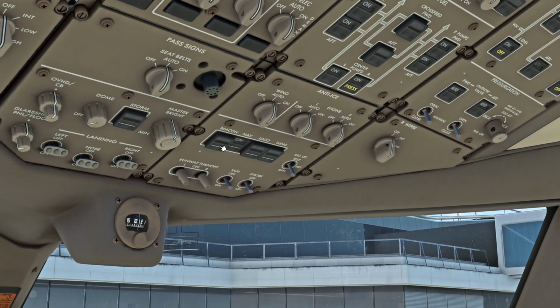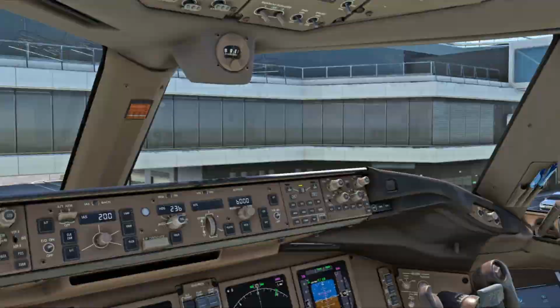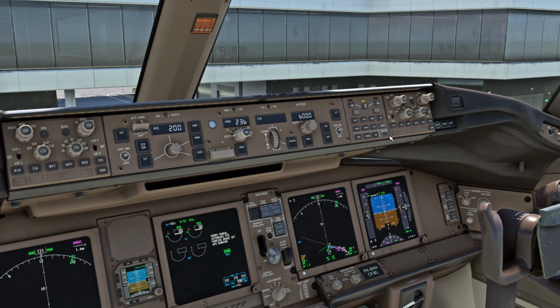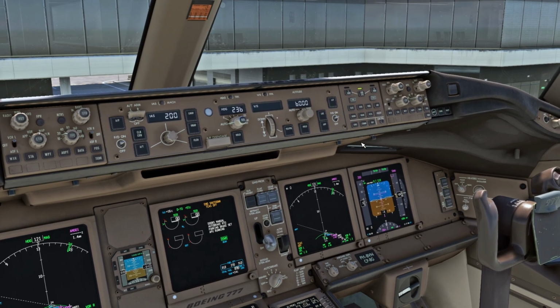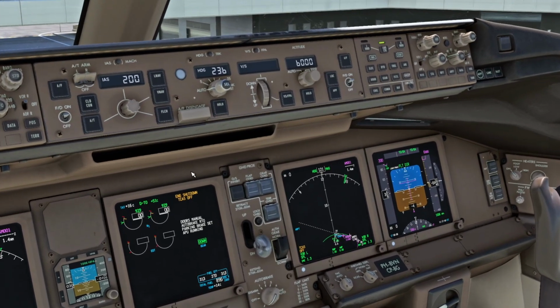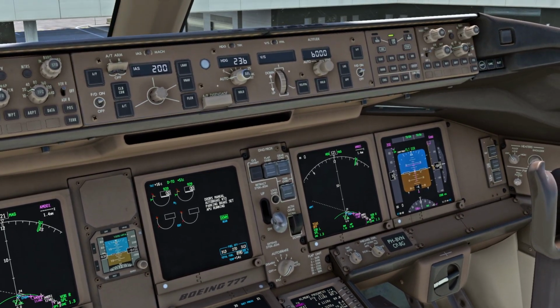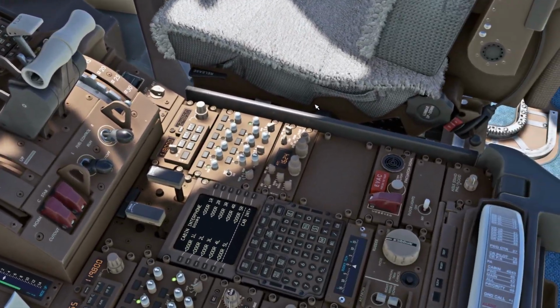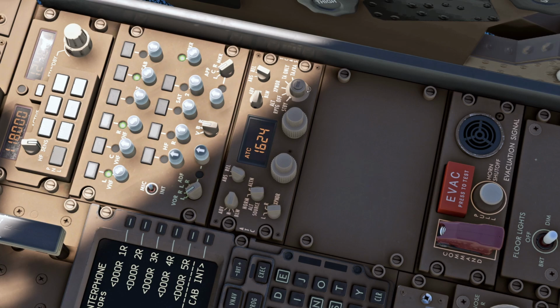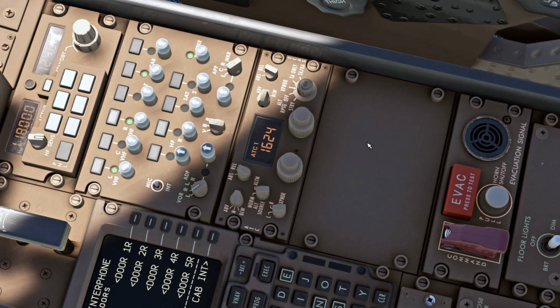Okay, so this is a normal sight. I'm going to turn on the beacon lights as well. There we go. Then we go down, and we're going to do a little recall to make sure we have the expected messages on the ICAS. In this case, engine shutdown, TCAS off are normal. So we're going to cancel that, and we're going to turn on the transponder. Before starting pushback, you want to put this to XPDR. It will turn the transponder on for ATC to see us, but we will not be using the TCAS functions yet. So this is a good position.